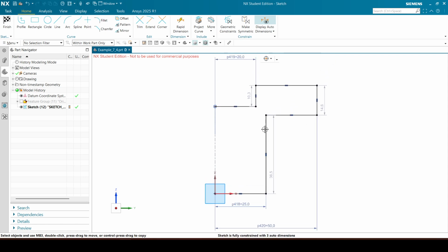It looks a bit short and fat, but that will get fixed quickly when we start adding the vertical dimensions. We're going to ignore the hole for now, since we're going to put that in later. The reason is that it is typically a feature that might change later, so you don't want to go in and mess with your sketch. Having it as an individual feature in your feature tree is good, because you can edit that one thing and not mess anything else up. So we're going to ignore that one and move along first to this dimension.